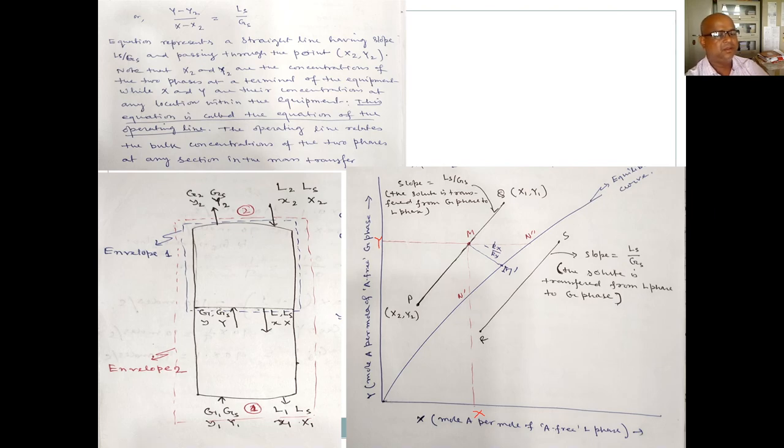Now, if you take one equilibrium curve, we are making this calculation based on the mole ratio, so you have to draw this equilibrium curve based on capital Y and capital X, because my calculation is based on capital X and capital Y. So if you have a small x, small y relation, you have to convert it in terms of capital X and capital Y. And you now know how to convert, because we saw this in the first problem.